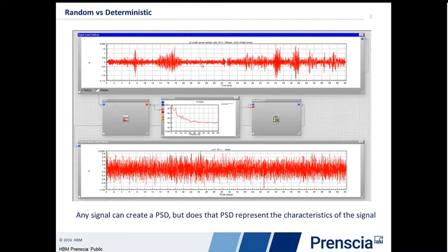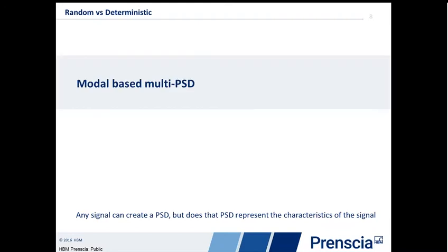One of the things we have to step back and think about when we take one route or the other is where my loads are coming from. If I have loads coming from things like wind buffeting, wave action, or engine vibration, those are very good candidates for the frequency domain and these approaches. If you know you have a very predictable load pattern, and the magnitudes change over time, then I probably want to take a time domain approach.